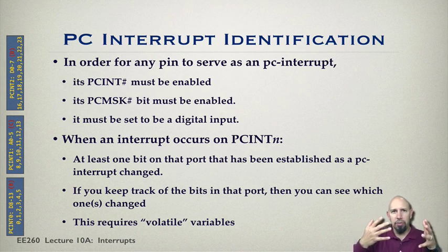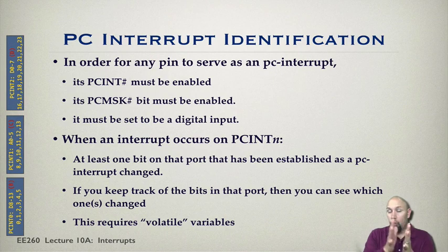When we get into the interrupt service routine, we compare the new value of what was in register C with what was originally in register C. We compare them. Okay, and if any bit has changed, or in particular, if the bit that we're concerned about, for example the bit associated with 12, has changed, then we know that that interrupt has occurred.